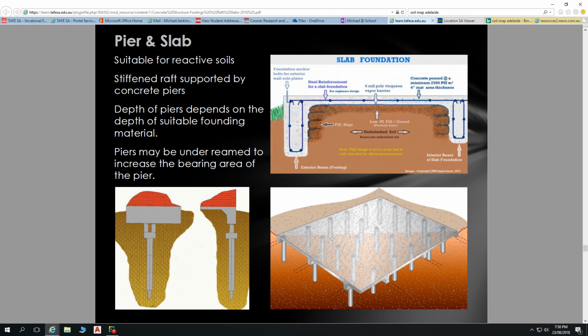So we build the first ring of the shell first, and go around that with a laser level to be picking things up, chopping, whatever. And some people have laser levels set on their bobcats, to get things just perfect. The technology is there to get things really good, really easily now.